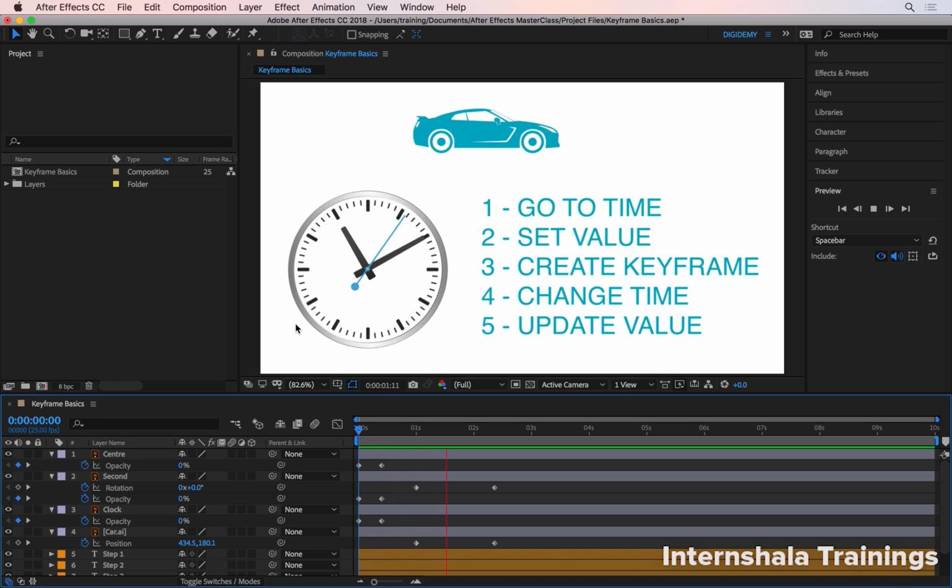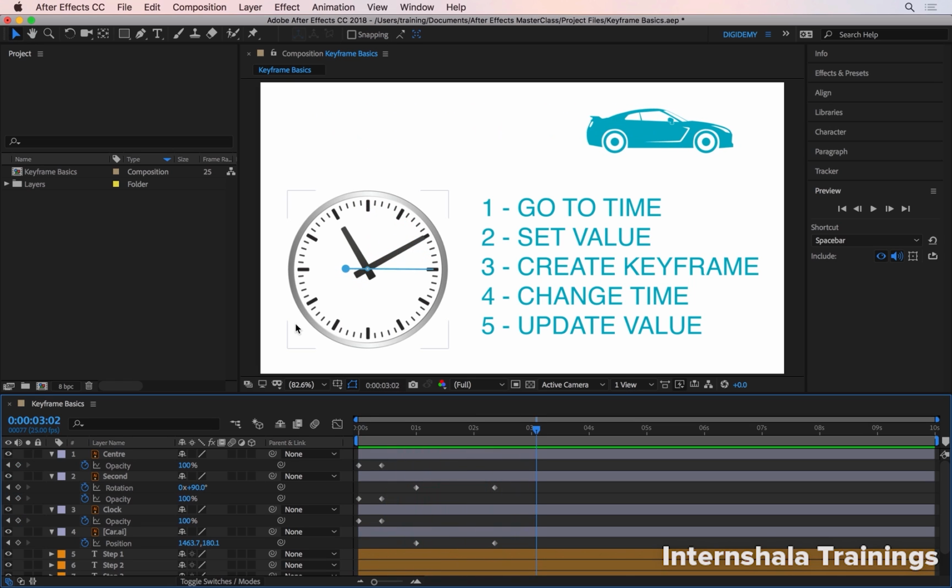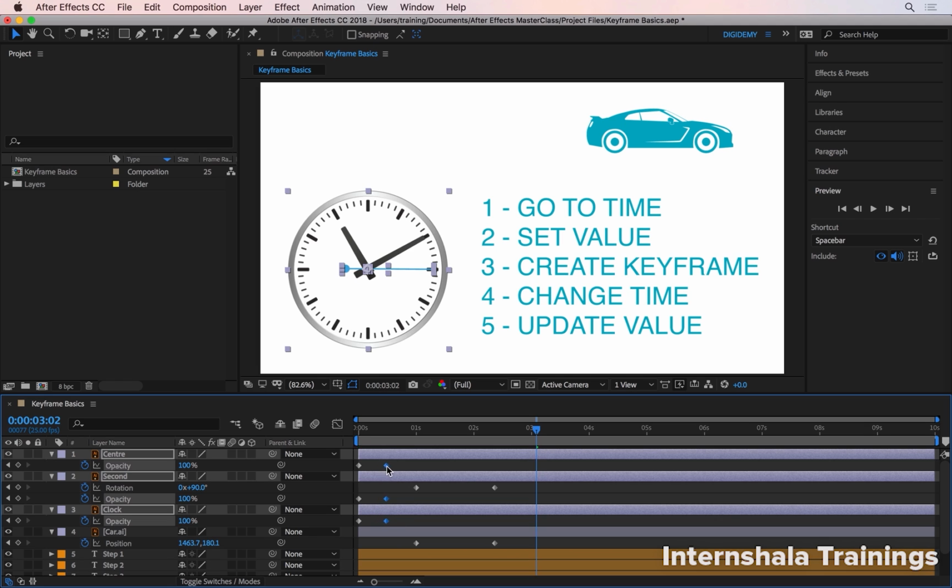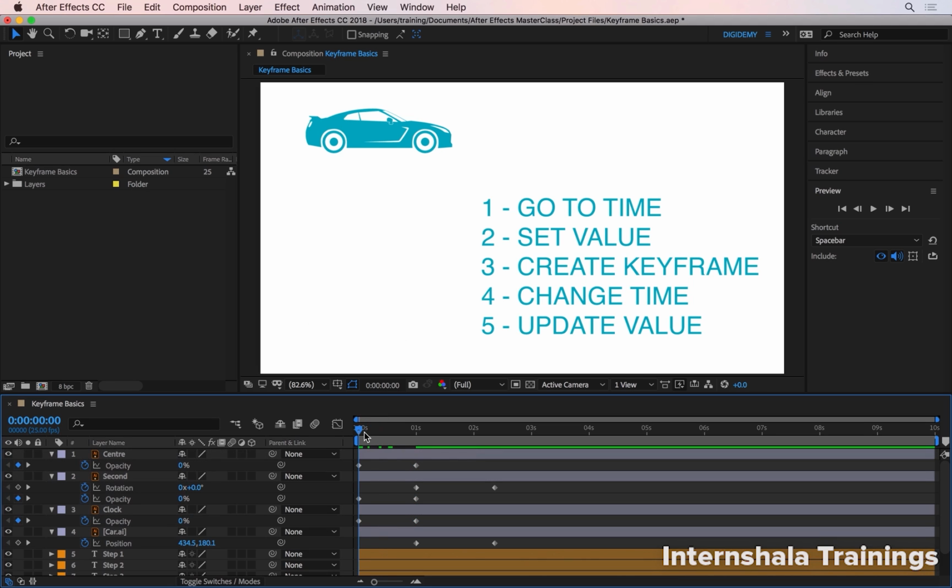Then the animation starts. And of course, I can slow these down. So if I select the second keyframes for all the opacity properties here, I can then drag them towards right, and then again hold the Shift key down. So these will snap to the first keyframe of the rotation here, or the position. And if I now play it, you'll see that the opacity animation is going to take 1 second to complete. And after that, the rest of the animations will start.